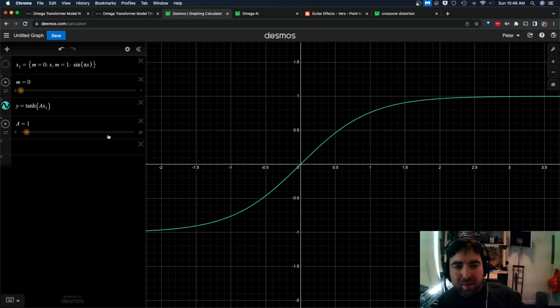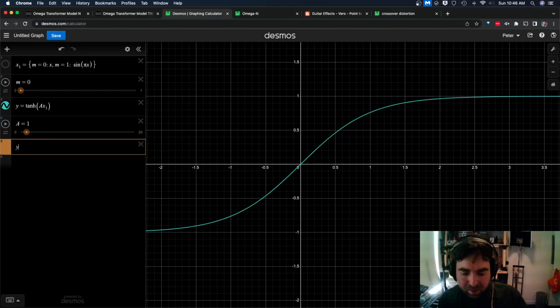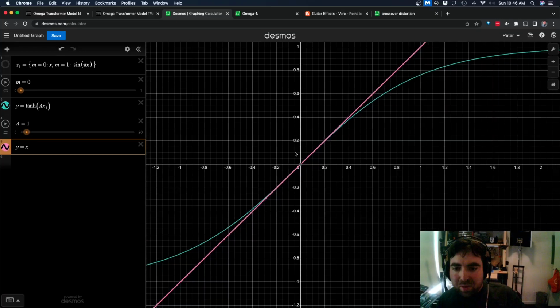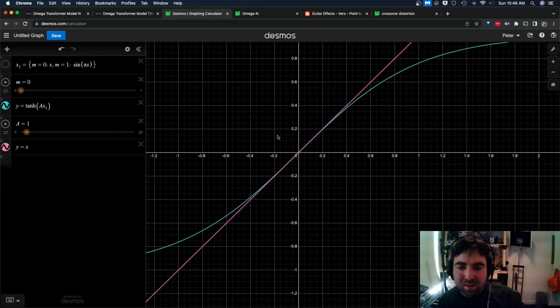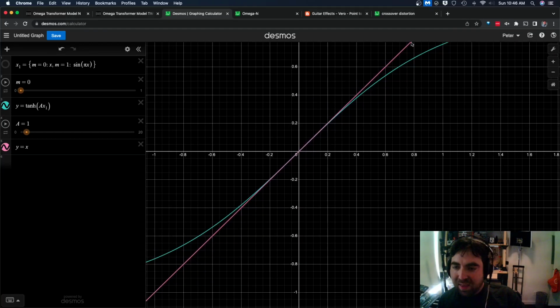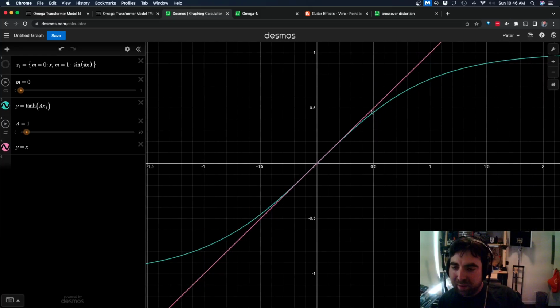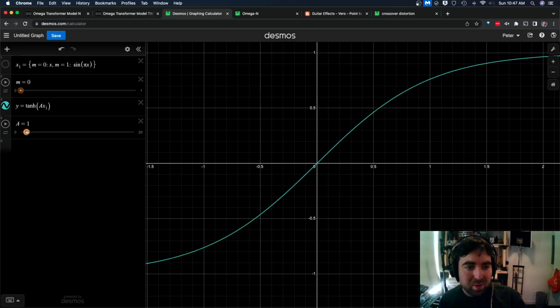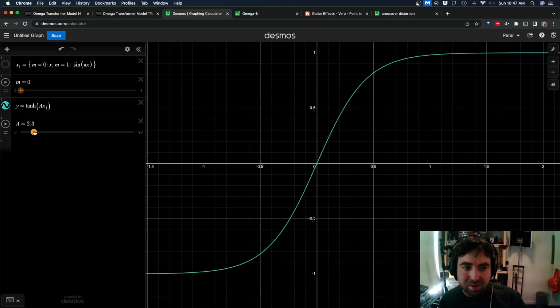I should also note that when it equals 1, when it's unity gain, the first almost half of the tanh function matches a linear function pretty closely, which is very handy. At unity gain, you might call this section a small signal response, so it's quite linear. Where it diverges on the ends, you'd say that's the large signal area where it becomes non-linear. And that's very useful for modeling analog circuits. So we see what happens to tanh when we increase the gain.